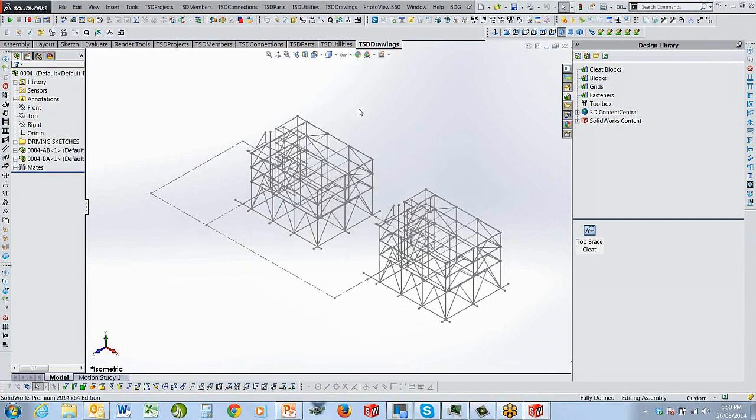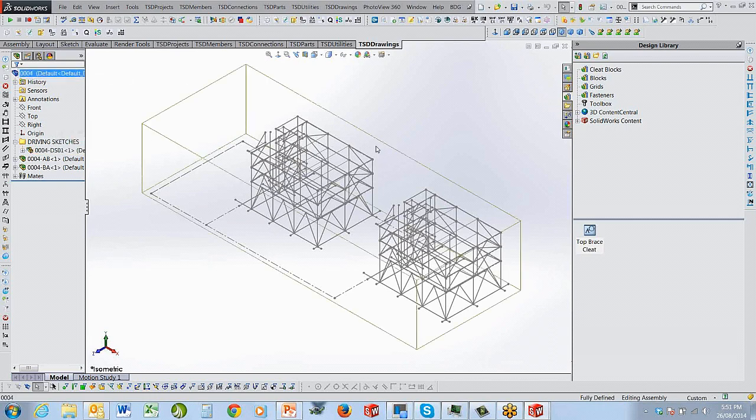Okay, so this is the top level assembly, and basically I've got my driving sketch, which is the top level project driving sketch. Now this is deliberately set up so that if you've got a team of people, your lead project draftee is the only one that has access to the very, very top level assembly, primarily because you don't want everyone in there, especially if you've got 10, 15 people working on a project. You want to be able to have that managed so that nobody gets access to this main driving sketch, because that can cause disasters. The reason for that is because if I go into this driving sketch, everything is actually set up off that.